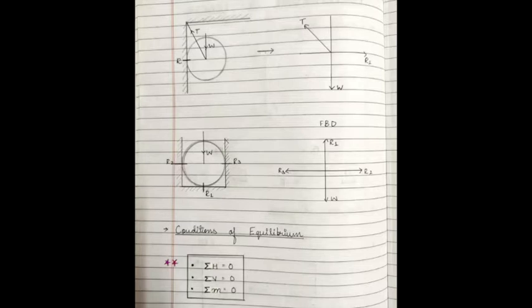The sphere is first in contact with the right side of the wall; that gives a reaction acting along the horizontal positive axis. Next, the weight of the body always acts vertically downwards. Then there is the rope, which has a tension in your second quadrant, that you can observe. The angle will be given in the problem, or you can assume it. That is the second example.